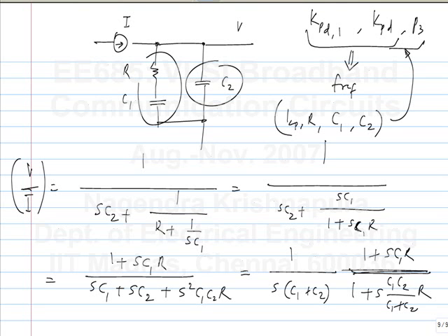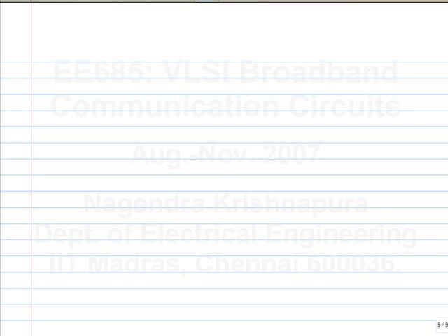So we now know how to make the phase detector and the loop filter. The frequency divider we dispensed with. The VCO we will see afterwards, but for now let's assume that we simply have a block which gives you a varying frequency in response to a varying input voltage.